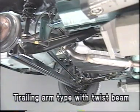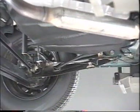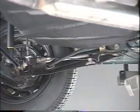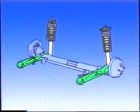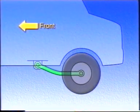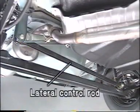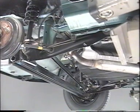Coil springs are also used in the trailing arm with twist beam type. In this type of suspension, left and right trailing arms restrict longitudinal movement by pulling the axle from the front. The lateral control rod provides lateral support. The construction of this type is simple and compact, and it makes for a soft, comfortable ride. It is used for the rear suspension of front-engine, front-wheel drive compact cars.